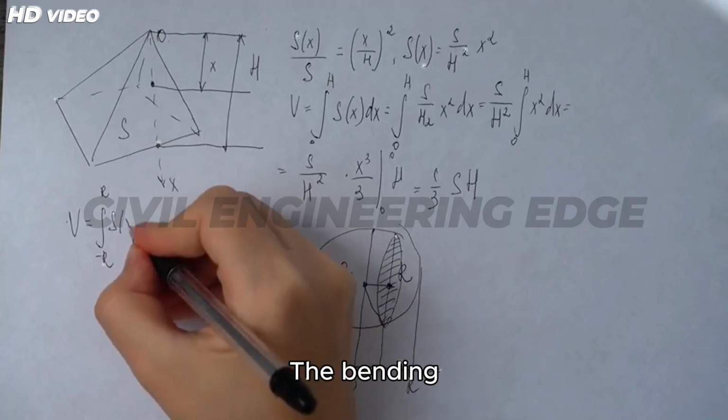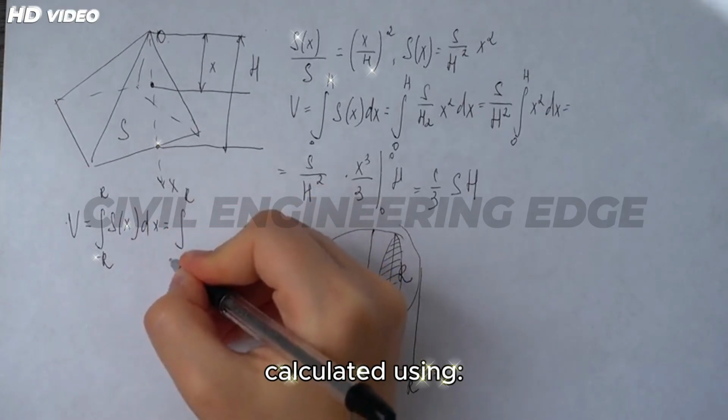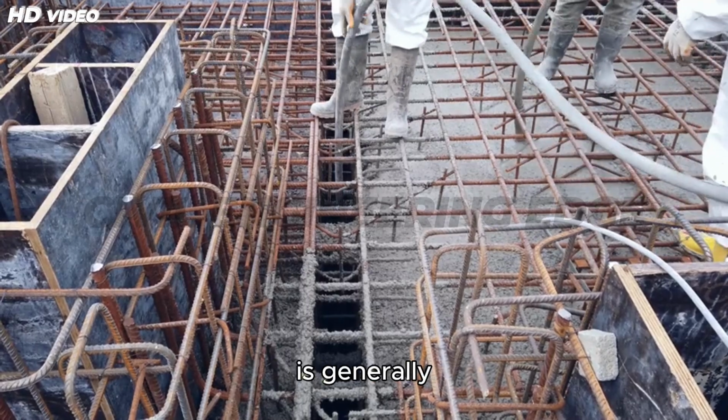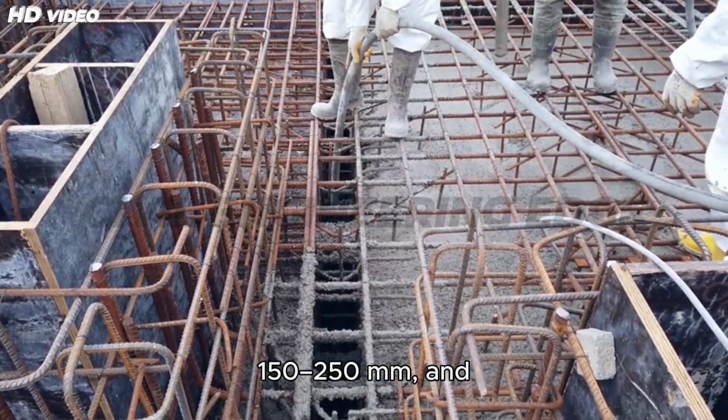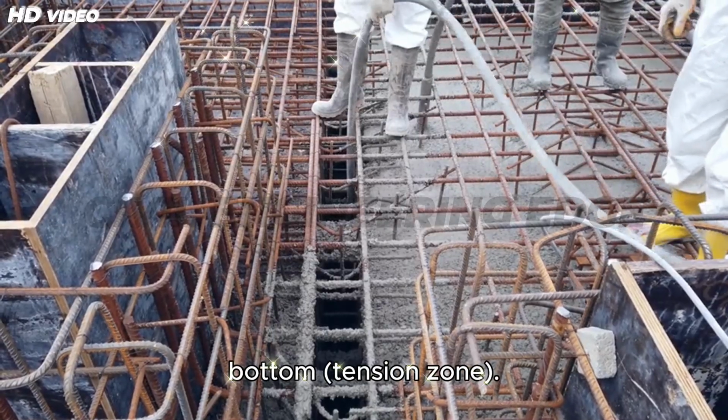The bending moment at the fixed edge is calculated using M equals W times L squared by 2. The slab thickness is generally 150 to 250 millimeters, and reinforcement is placed at the bottom tension zone.